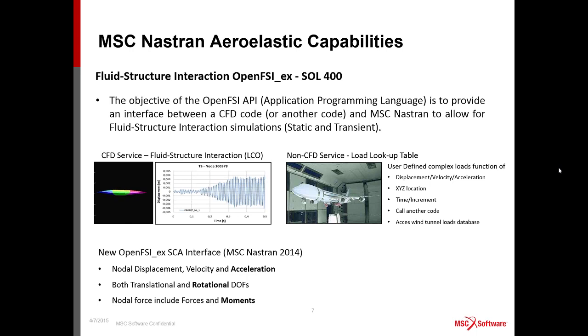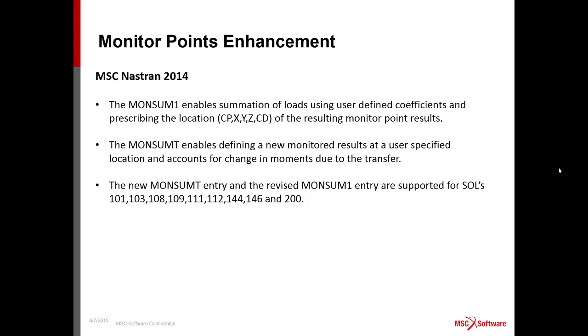Okay, this is very interesting because, as I'm going to show you later in this presentation, it allows us to use the spline technologies with the 6 degrees of freedom that we have available in Nastran. Something about the monitor point enhancement, okay? In the 2014 Nastran version, okay, we implemented some ARM that enables the summation of load using user-defined coefficients and prescribes the location of the monitor point of the resulting monitor point results, okay? This is what's different in 2013.